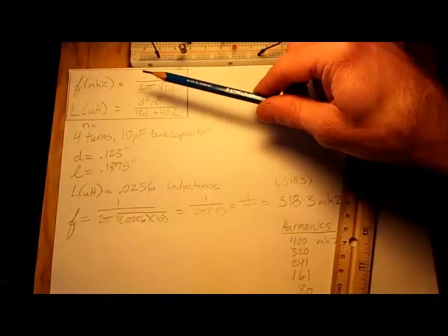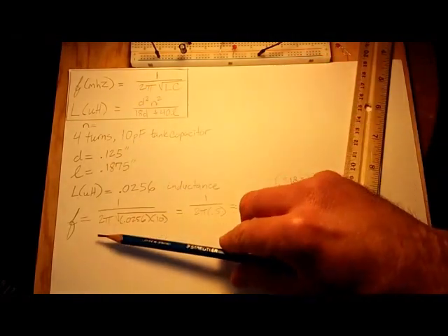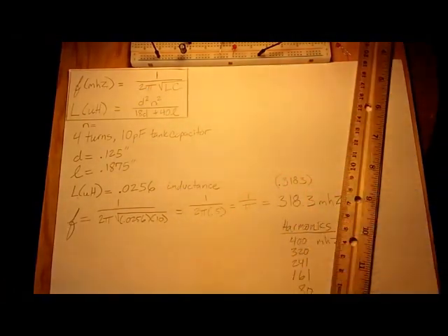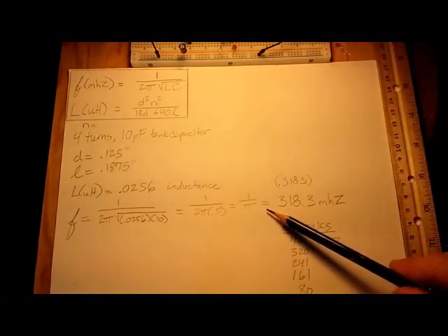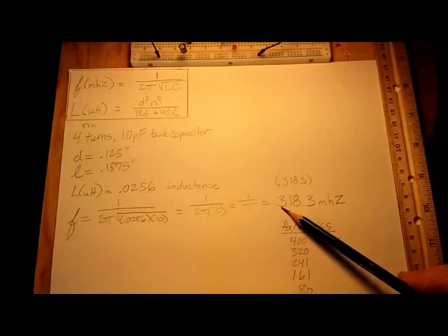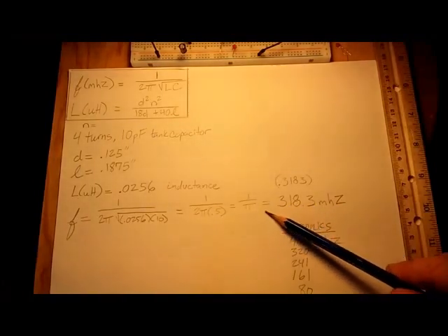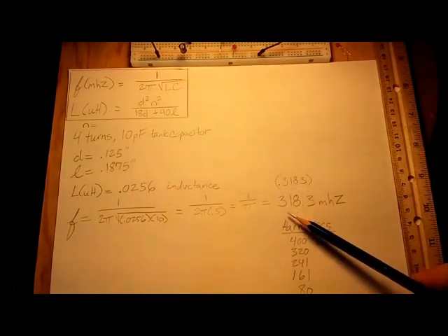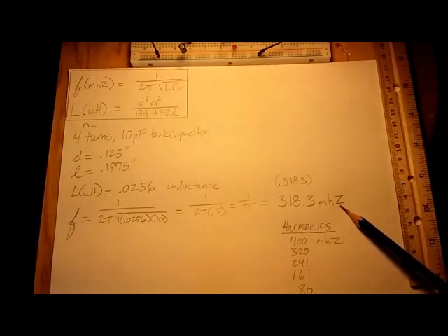And then we can plug that value into the frequency formula, the resonating frequency formula. And following through here, we're actually going to come up with 1 over pi, which is an interesting value. So we should be transmitting at 318.3 megahertz. Now you're going to get a decimal value from this. Just carry that over to the thousands place, and you're going to get your megahertz.